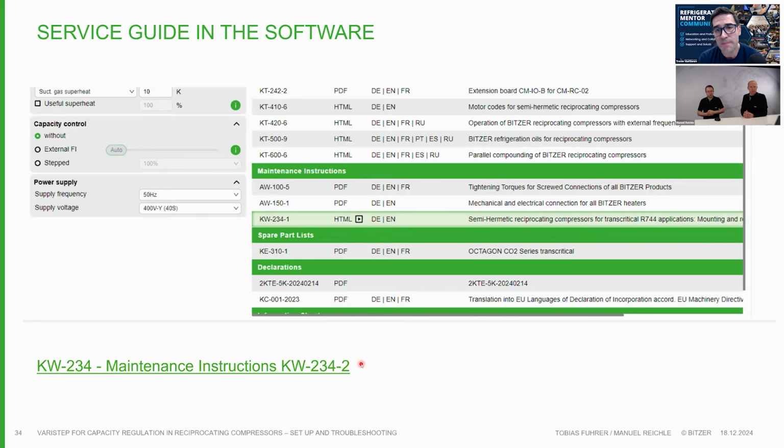Yeah, the sound changes because we go from basically a 4-cylinder operation to a 2-cylinder operation. So the compressor configuration gets a little bit imbalanced. We try to make it as balanced as possible also for the unloaded situation, but the reaction of the compressor, from its vibration to the system, is changing, and therefore you can have also noises, of course.